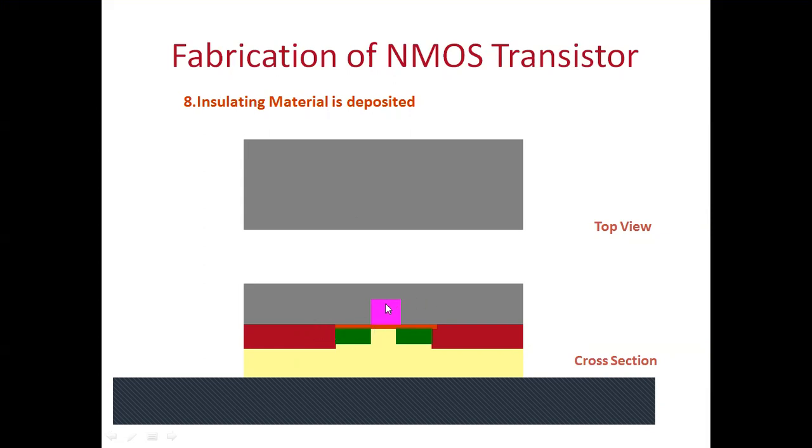So material is deposited everywhere, insulating material, because we have to take the contacts. Then contact mask. So this is another mask, contact mask, which creates the window, because we have to take the contact to substrate, source, drain. So this is to make the windows. So then after photolithography, you can see here that windows are created by all process, photolithography, exposure to ultraviolet radiation.